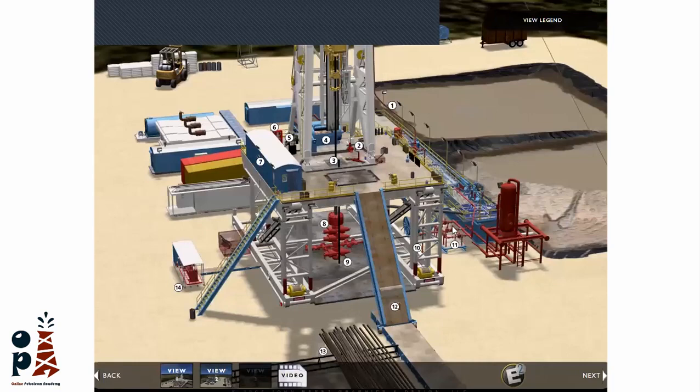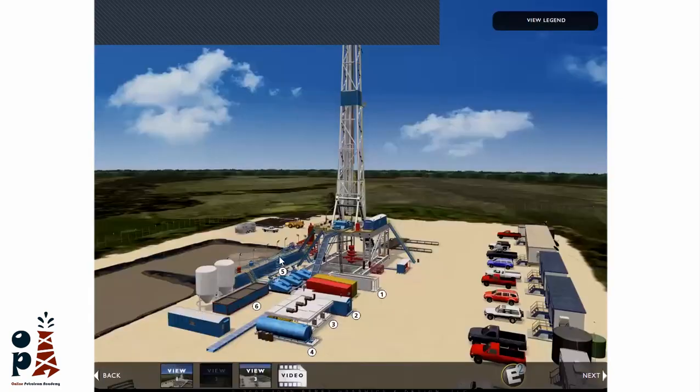Okay, so this is the choke manifold through to the mud gas separator. Then these are our tanks. We start with the sand trap and shale shaker, then the desander, desilter, mud cleaner, then the mud gas separator, mud degasser, and then our tanks. And here you can see the mixing area. From this view you can see the tanks, and you will find the rig pump. You will also find the waste pit, which is just below the shaker area, so that we can receive the cuttings in this area.